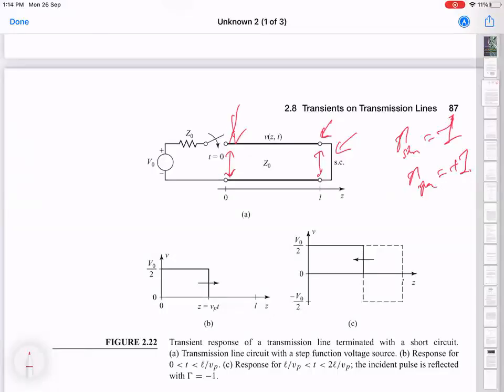And what happens at this point? You again have a matched situation, because you are propagating from a Z0 transmission line to a Z0 load. The source is ideal, what's called the Thevenin model, with zero impedance by itself, so you don't worry about it. When the signals reach the source, what matters is the impedance from this point to ground, and that is the same as Z0.